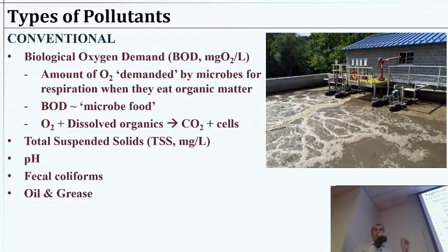Bacteria will be doing the same thing. For every sugar molecule or every other molecule, whatever molecule they're eating, they're oxidizing, converting oxygen to CO2. They're getting energy, maybe they're building cells with it. Those are the processes. So every X amount of food, they're going to demand Y amount of oxygen. Okay, they will have some proportion there. So the more waste in the water, the more oxygen the bacteria will demand once they're able to eat it. So that's why we add in lots and lots of bubbles for our wastewater. So it'd be a waste-activated sludge system we see here.